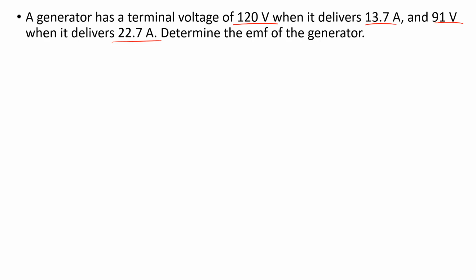And as we increase the external resistance to infinity, our terminal voltage is going to approach the EMF, which is what we're looking for. If we're thinking about that in terms of current, let's just do a graph of voltage against current. As our external resistance goes to infinity, our current goes to 0, and that's when our voltage is equal to the EMF.